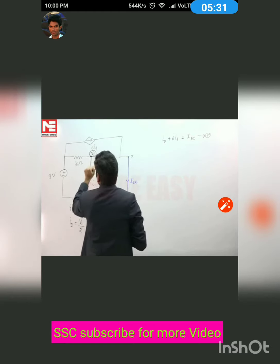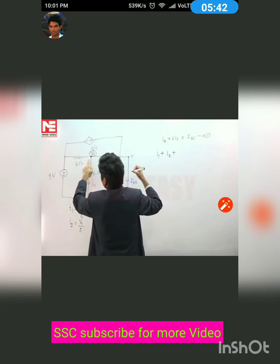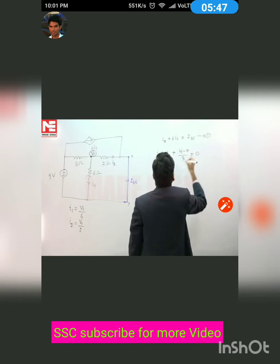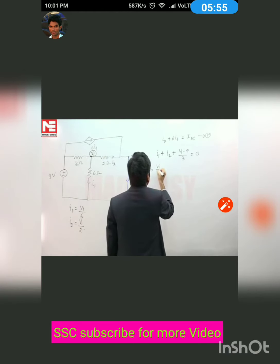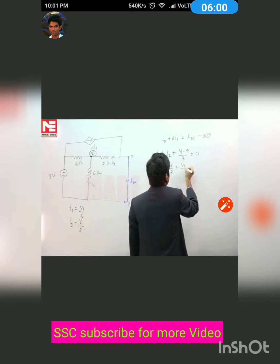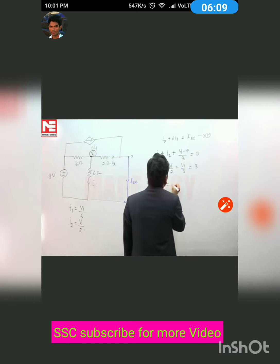Suppose this point voltage is V1, so we have I1 equal to V1 by 6, and I2 is also equal to, since this is short circuited, V1 by 2. Now if we apply KCL at this point, then I2 entering plus 6 I1 entering is equal to ISC, equation number 1, the short circuit current. Also, if we apply KCL at this point, we have I1 outgoing plus I2 outgoing plus (V1 minus 9) by 3 equal to 0. Putting in I1 and I2: V1 by 6 plus V1 by 2 plus (V1 minus 9) by 3 is equal to 0. Solving, the V1 value is equal to 3 volt.